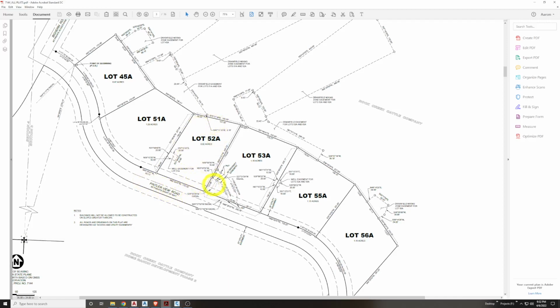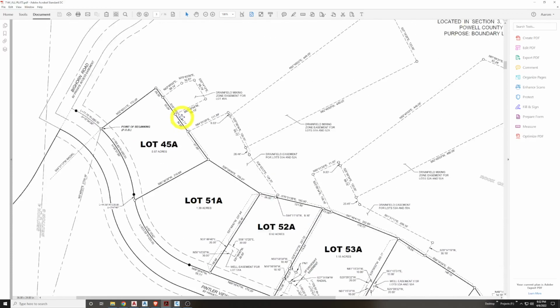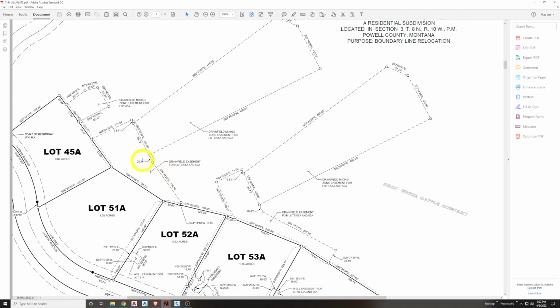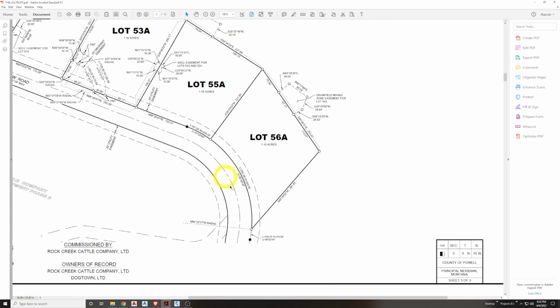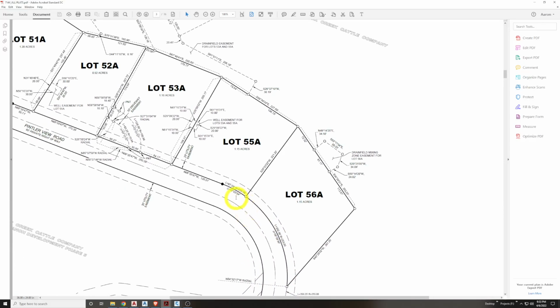I drafted up a bunch of very precise lots with annotations showing bearings, which is angles or vectors, basically, and distances along to very precisely show how these lots would be laid out, showing little drain fields, because there's no public sewer out here, so they had to have on-site sewer, basically drain fields and various things, and showing all kinds of little monuments to show what will be set, what will be documented, the measurements.